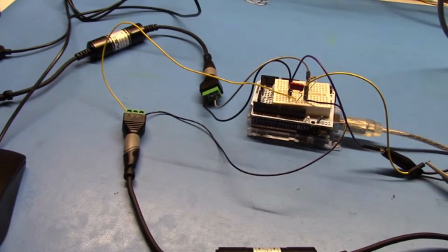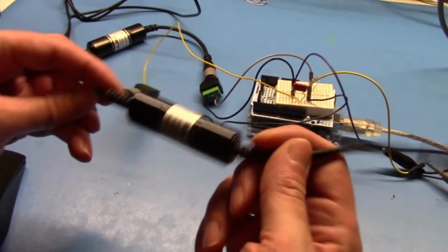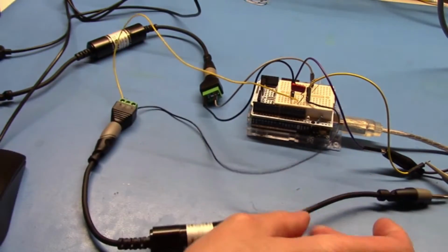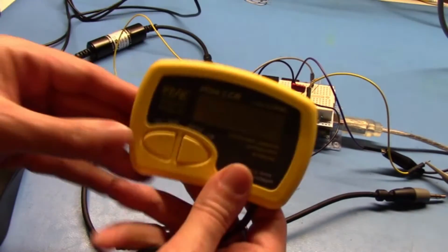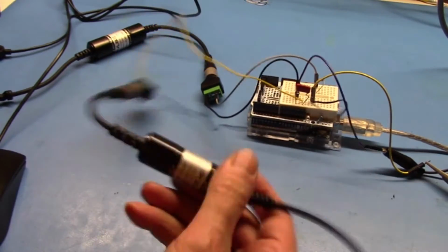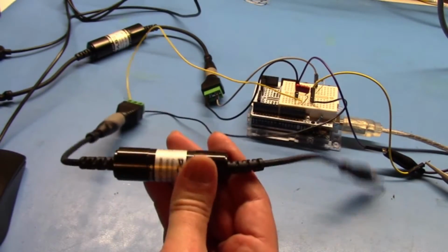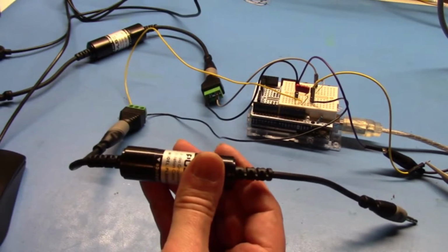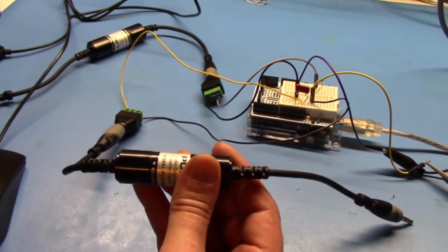Okay, so I thought I'd try and think of a way to demonstrate the LCR resonance. And to do that, I was wanting an inductor that would work nicely in the audio region. And it just turns out that the isolation transformers work perfectly for this. So I initially used one of these excellent little Peak LCR bridges to measure the inductance and series resistance of this device, and it comes out to be about 2.8 henries of inductance and 98 ohms of series resistance.